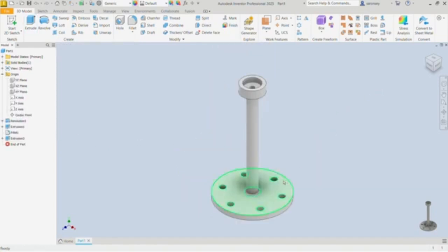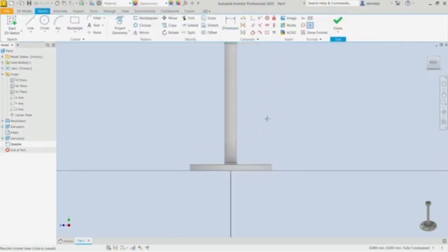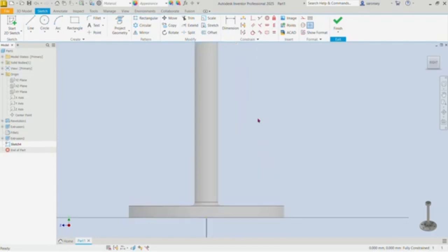For the next step, we want to model the ribs. To do that, let's pick a plane to work on, and so open up the default planes, pick the YZ plane. Let's create a sketch on that plane. Let me pan down a little and even zoom in, so we can pick the line command. Let's draw a line from this vertical line and lock that onto the horizontal line down here. You can right click and then OK.